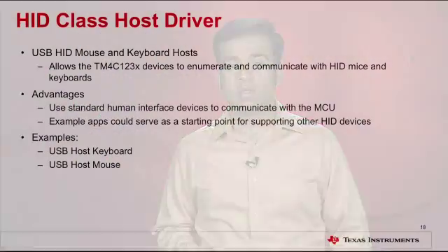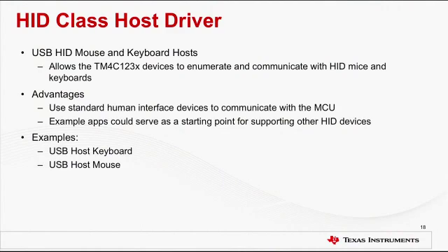One of the benefits of a well-defined specification like the USB HID class is the abundance of device drivers available in most modern operating systems. The USB HID class devices and their basic functions are defined in USB Implementers Forum documentation without any specific software in mind. Because of these generic descriptions, it is easy for operating system designers to include functioning drivers for devices such as keyboards, mice, and other generic human interface devices. The inclusion of these generic drivers allows for faster deployment of devices and easier installation by end users.